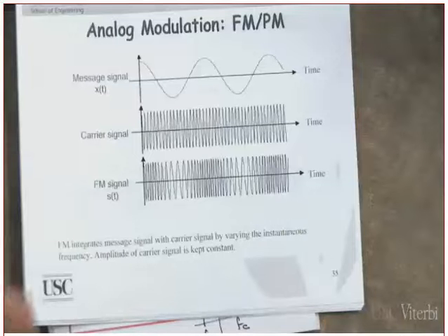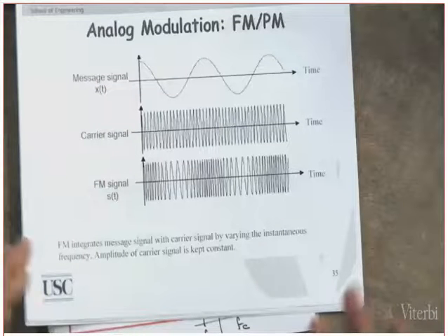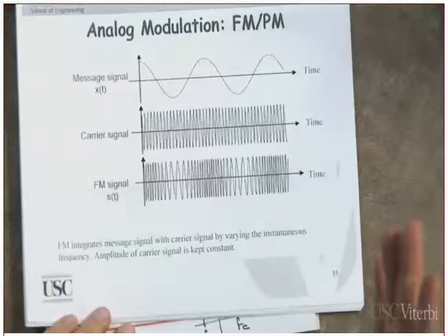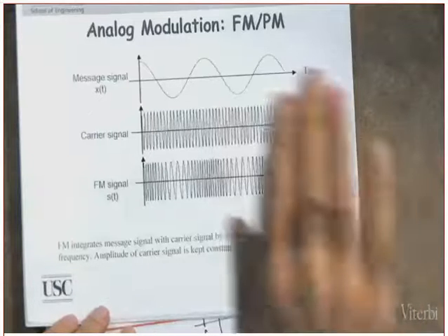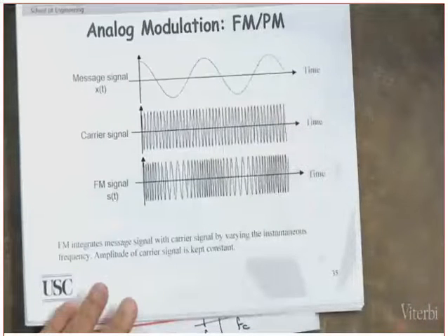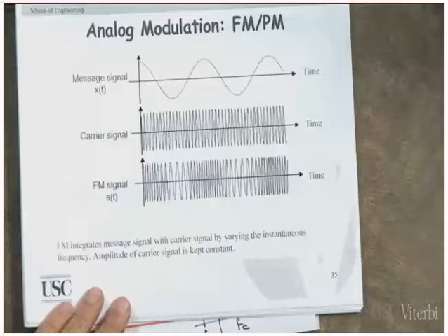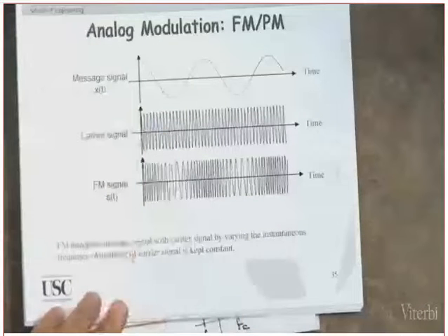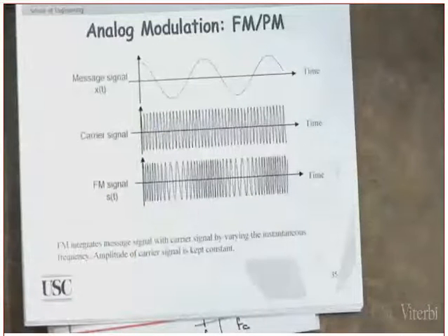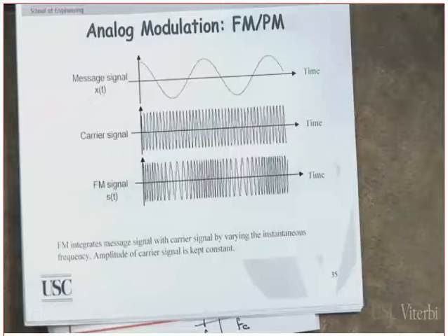Clear? So in an FM receiver, as we will see later on, one of the circuits that we need to design is a limiter, to try to get the amplitude back to be constant. Are you following me or not? However, a limiter is a nonlinear device, which means that it will generate harmonics and so on and so forth. Clear? Oh, by the way, later on we will see the harmonics are not really the big issue.